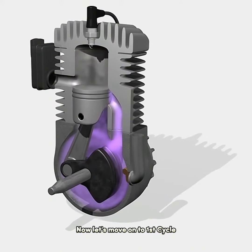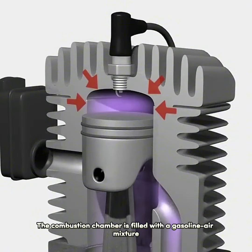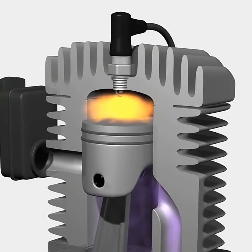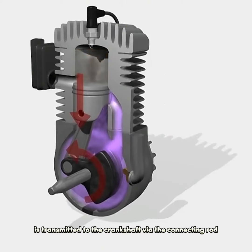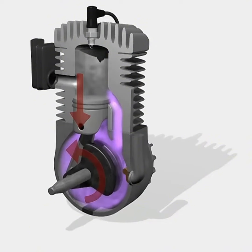Now let's move on to the first cycle, the work cycle. The piston is at the top. The combustion chamber is filled with a gasoline-air mixture. The spark plug ignites the mixture with a spark, and by the explosion, the piston is pushed down. This pressure is transmitted to the crankshaft via the connecting rod, so the crankshaft rotates.